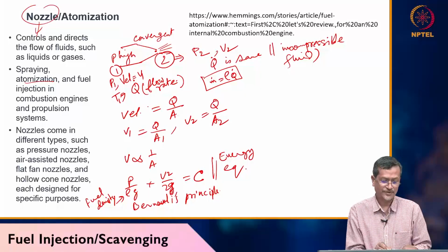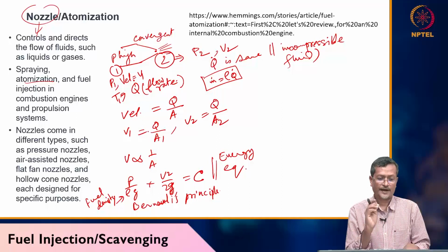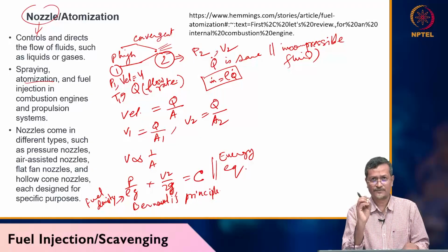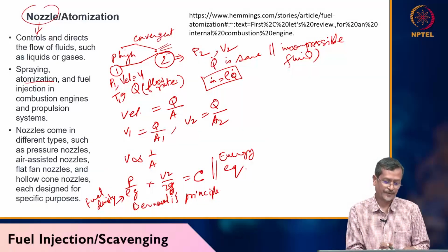In a non-premix combustion system, fuel is atomized in air before being burned. The fuel droplets are then vaporized in the high temperature environment in the combustion chamber. Vaporized fuel takes larger space. Atomized fuel will take lower space because it is still liquid. Vaporized fuel will take larger space because vapor will be expanding. Then this displaced air dilutes the air fuel mixture.